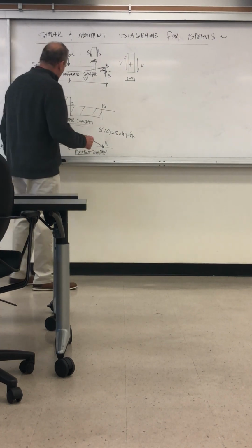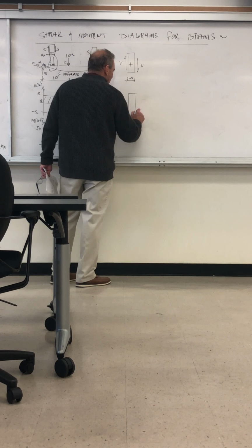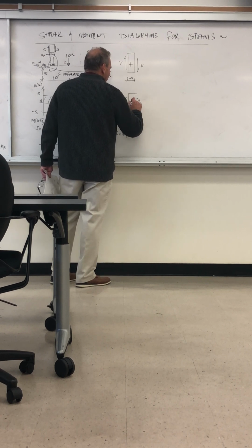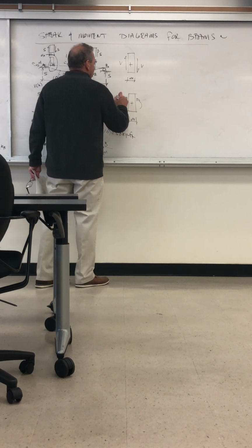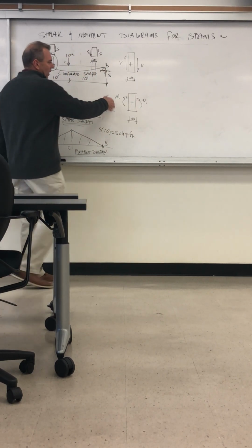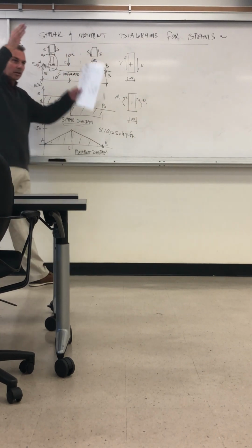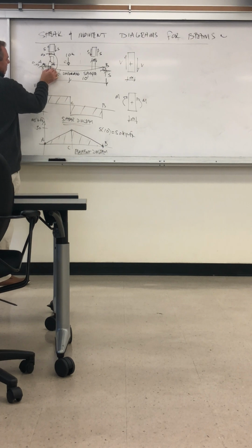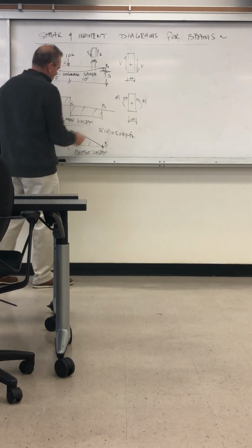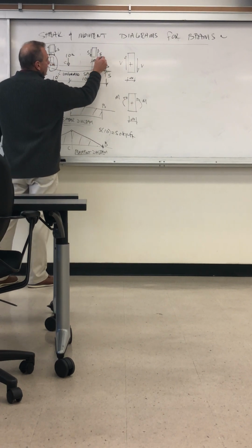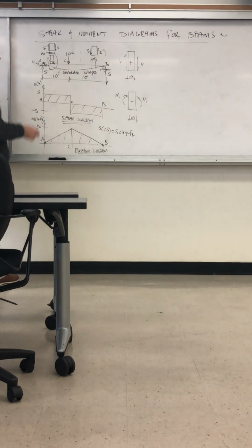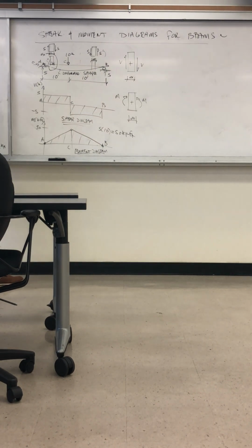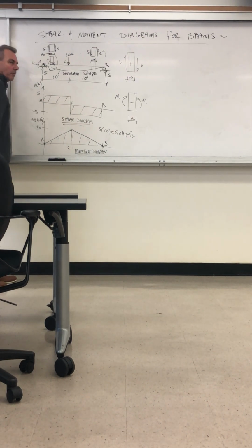And then let's add what's positive and negative moment. If we take again the slice of the beam, our definition of positive moment is this. On the left that way, M. On the right this way. If you have a moment applied here, by statics, this has to be on the other side of it. If you cut out a whole segment, it has to be equal and opposite. Looking at this slice, you have this force times its distance. That's clearly a moment like that, which is consistent with this. This force times this distance is a moment this way, which is also consistent with what's on the right there. So that's why this is all positive moment and there's no negative moment, whereas in shear, there's positive and negative shear.